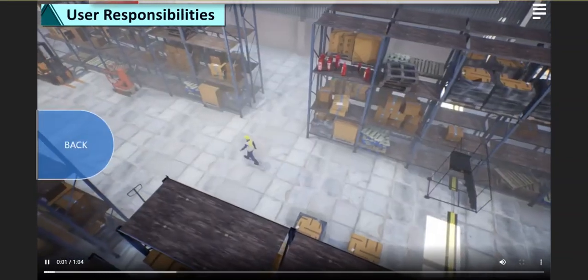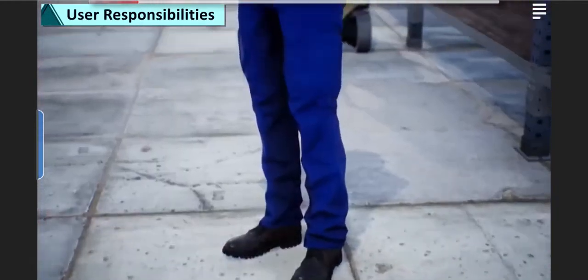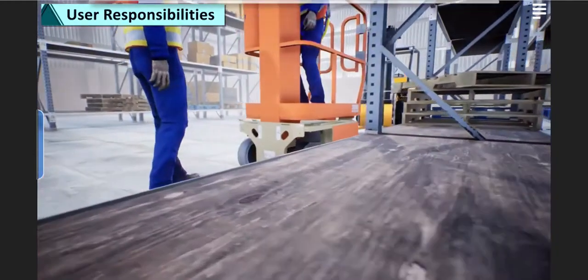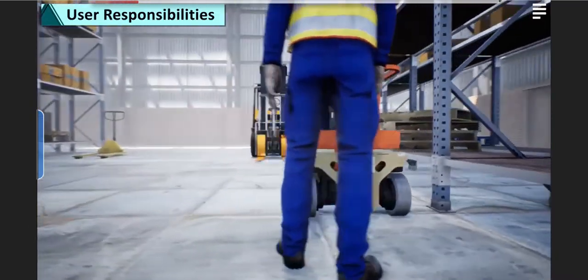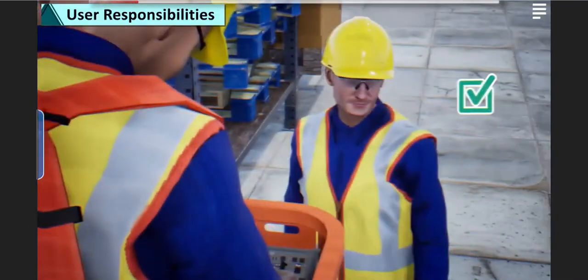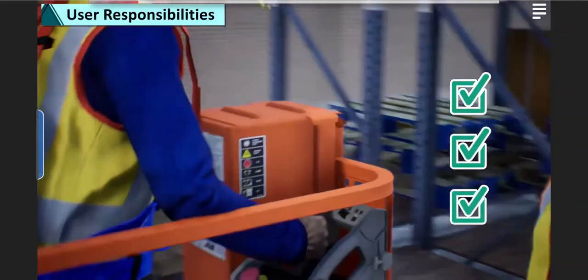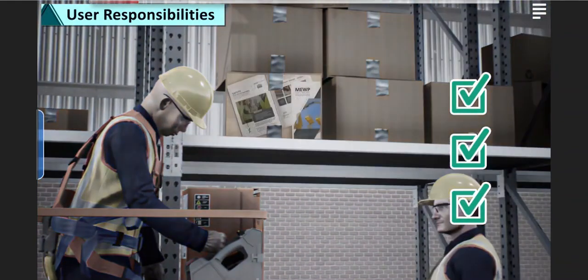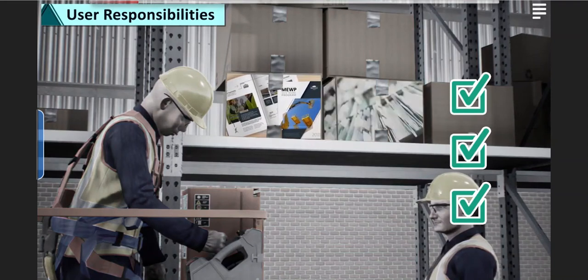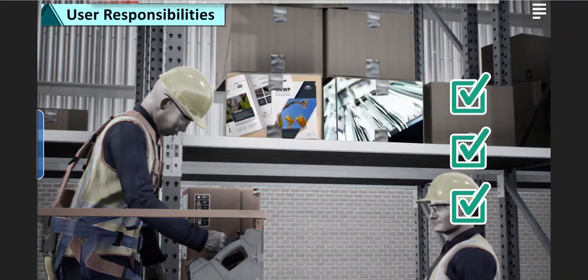The user has some of the biggest responsibilities when it comes to MEWP safety. Remember that the user is the person who is immediately responsible for the MEWP. The user is responsible for ensuring that any and all personnel who operate or occupy the MEWP are properly trained, qualified, and authorized for their job duties. This includes developing and implementing a written safe use program and ensuring retention of all applicable records.